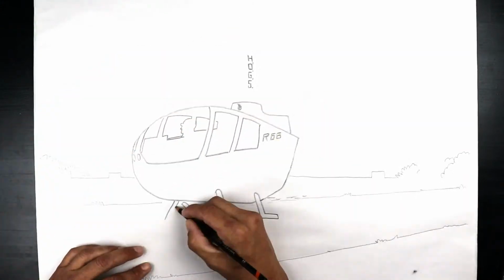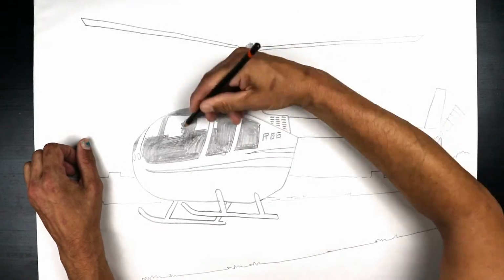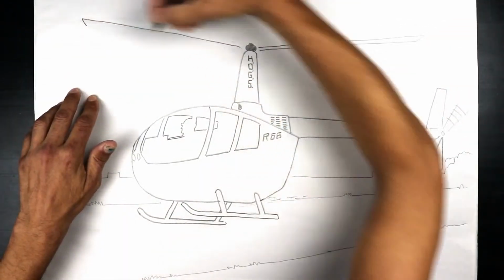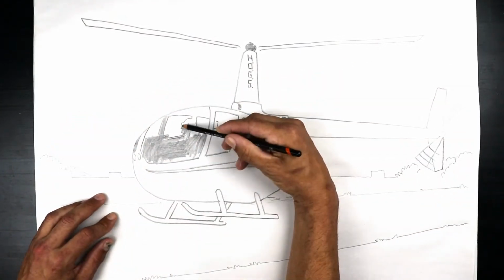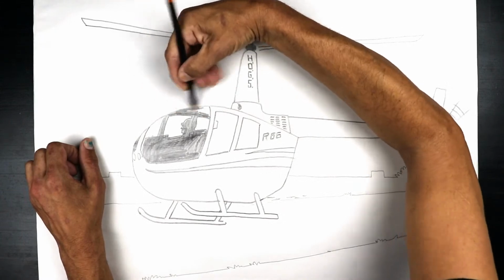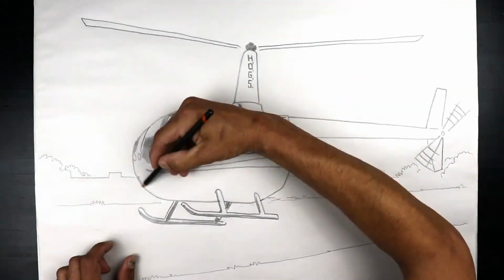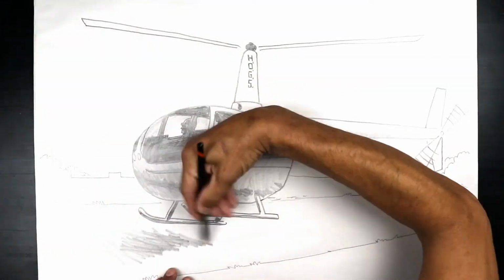Once you've applied lift and you've gotten the helicopter up off the ground, in this example in a hover, the blades are going to cone up due to lift and the weight of the helicopter is being suspended by that rotor system. Now, depending on which helicopter you're flying, they could be coning up due to hinges that are allowing them to move up, or they could be coning up through bending of the blades.